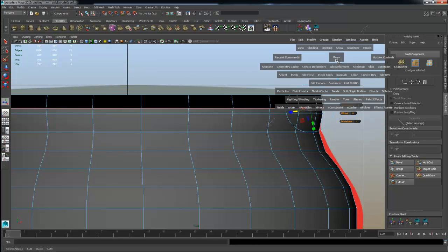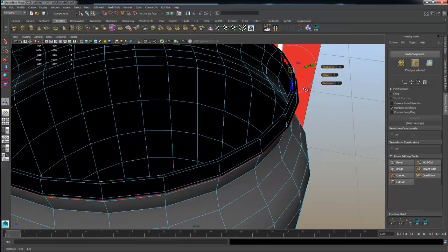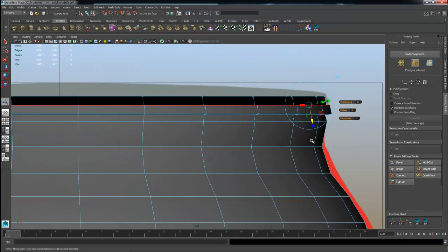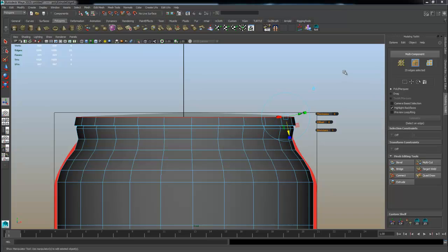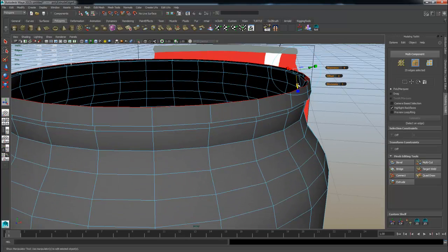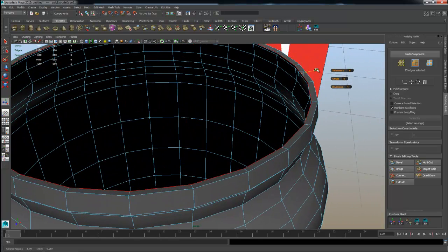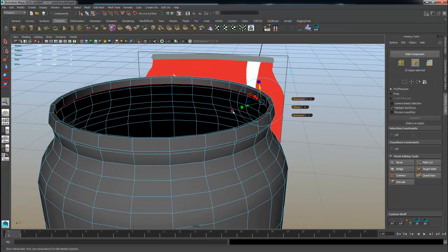As I do that, I quickly want to explain the reason why I'm doing it as an edge extrusion instead of face extrusion. When you're doing an edge extrusion, it's a lot cleaner in regards to face normals, and it helps you to work with a lot less information at a time. So I first deleted the top section, and now I'm doing edge extrusion so that it gives me a little bit better of a setup process for extruding that specific detail. I could have done the same thing with face extrusion. The only difference is when you're doing face extrusion, some of the faces might overlap, and that causes some issues.